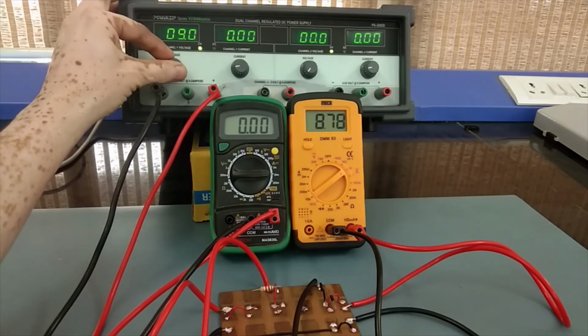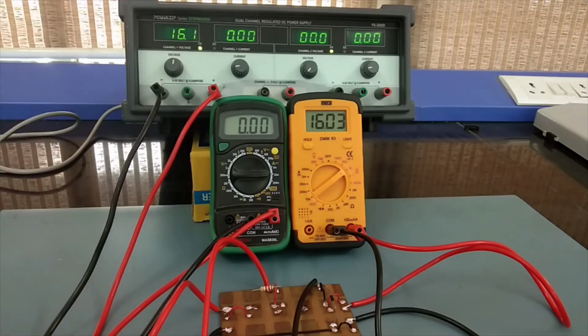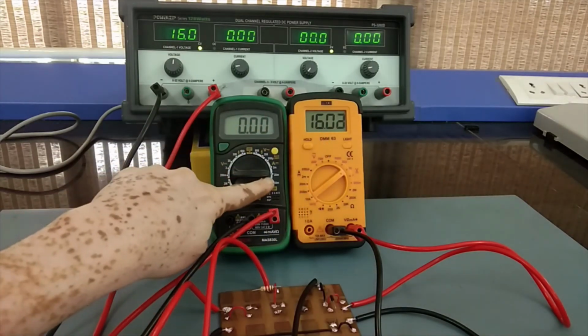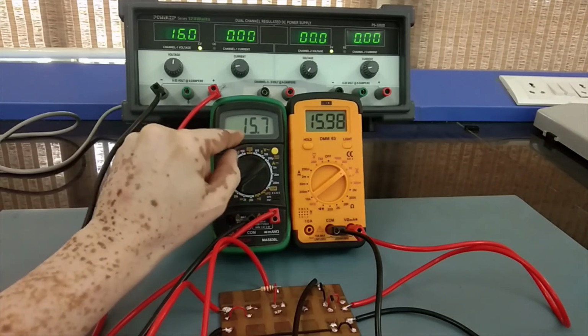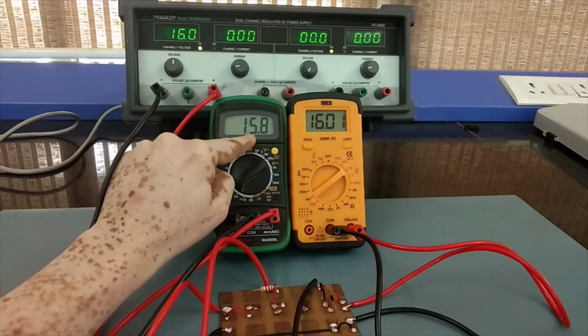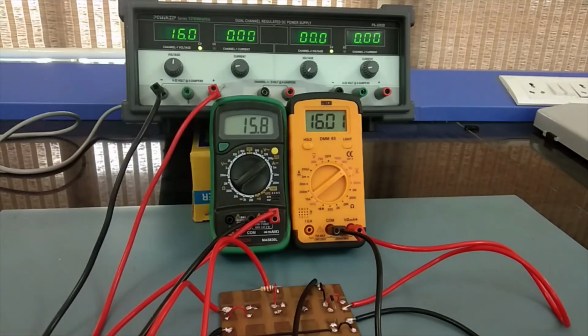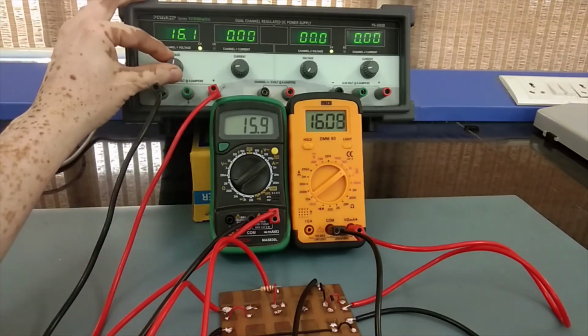Okay, so I will increase the voltage. You can see I have taken it up to 16 volt right now. 16 volt is being applied across the diode and you find no current in milliampere range, but in microampere you can find it is 15 microampere. That means yes, your minority charge carriers are responsible for this feeble amount of current that is passing through the diode. I will go up to 20 volt